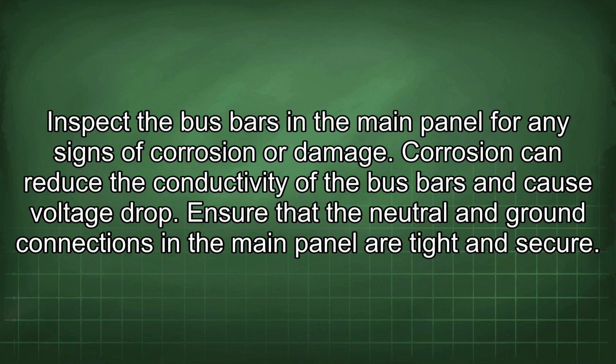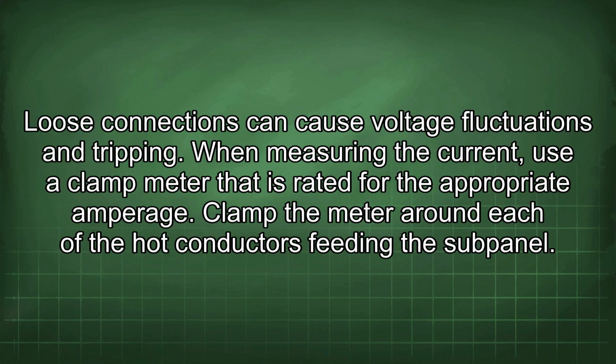Ensure that the neutral and ground connections in the main panel are tight and secure. Loose connections can cause voltage fluctuations and tripping.